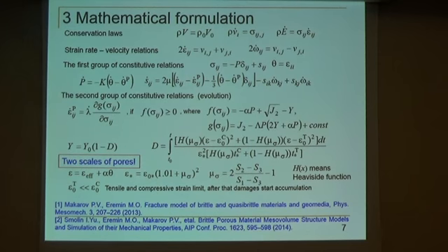The nature of inelastic deformation is different from ductile materials, but the approaches are rather similar. But to describe the so-called pressure-sensitive behavior of quasi-brittle materials, we use the plasticity function, which includes pressure, not only the J2.